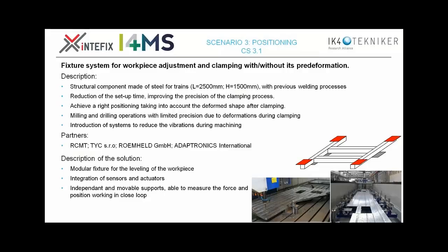So the idea is to include modular fixture elements for leveling the workpiece and to move the workpiece to the right position in the machine workspace. And basically, this will be done with independent movable supports, able to measure the force and the position, and work in a closed loop. So the different elements will be controlled by a single controller.